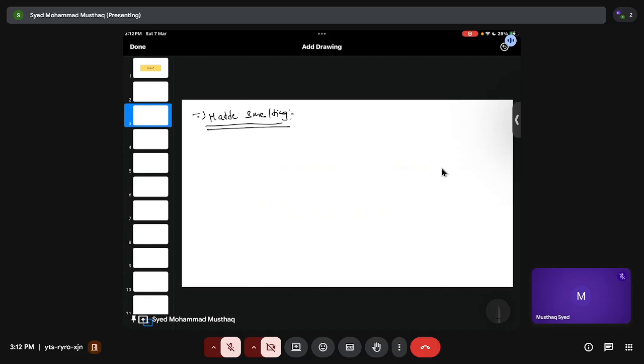And we mostly see this in copper, right? Chalcopyrite. When you are dealing with chalcopyrite, you will end up with Cu2S and FeS, right? So you will have a mixture of sulfides when you do the melting. That is called matte smelting.